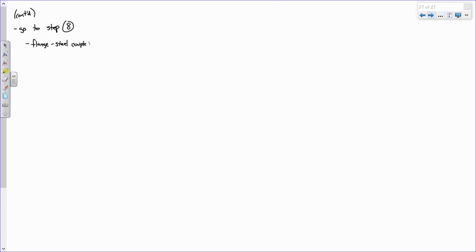So I don't want you to think, when I say here's the formula for ASF, and it's 0.85 FC prime (B minus BW) times HF all over Fy, where in the heck did you come up with that formula? Did I just pull it out of thin air, break out the crystal ball and say that's the answer? No, it's just basic, C equals T, okay?